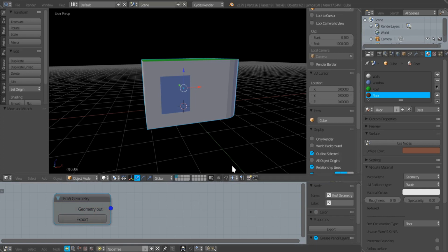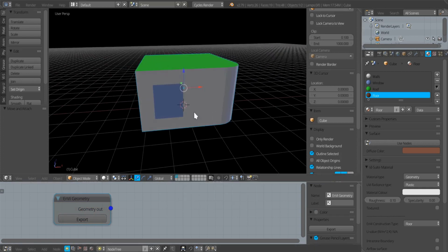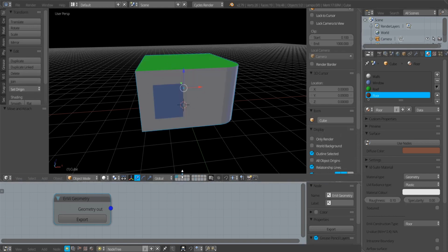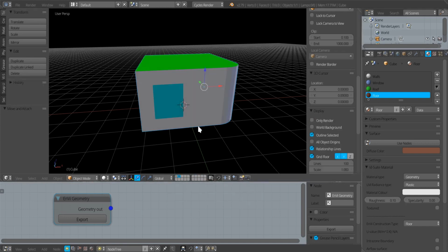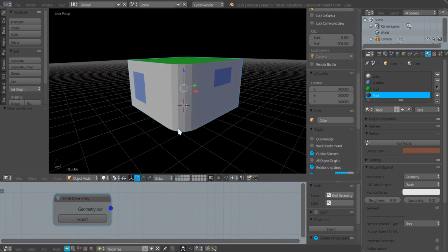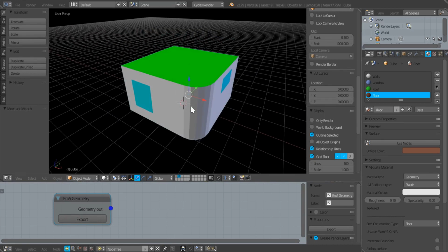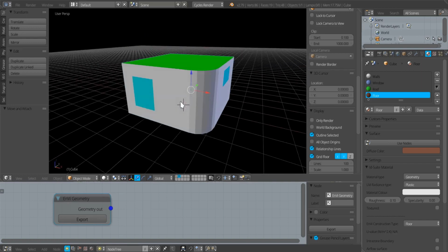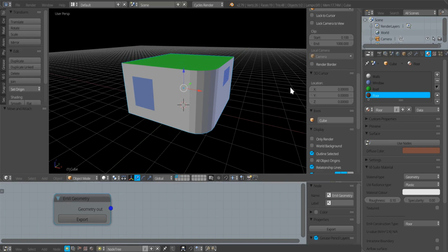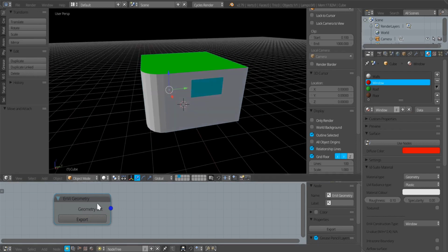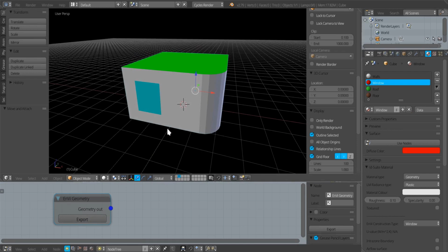So now if I export that, nothing's changed here, but we'll notice I've constructed my geometry on layer 1. These are Blender's layers, 20 in all. I now see I've got something on layer 2, and layer 2 is a copy of this original geometry. This copy is made during geometry export. And now we have specifically colored these different types of surfaces according to a schema. If, for example, I make my windows red in my original geometry and then export, whatever color I made things in the original geometry, the exported geometry is colored according to a particular schema.